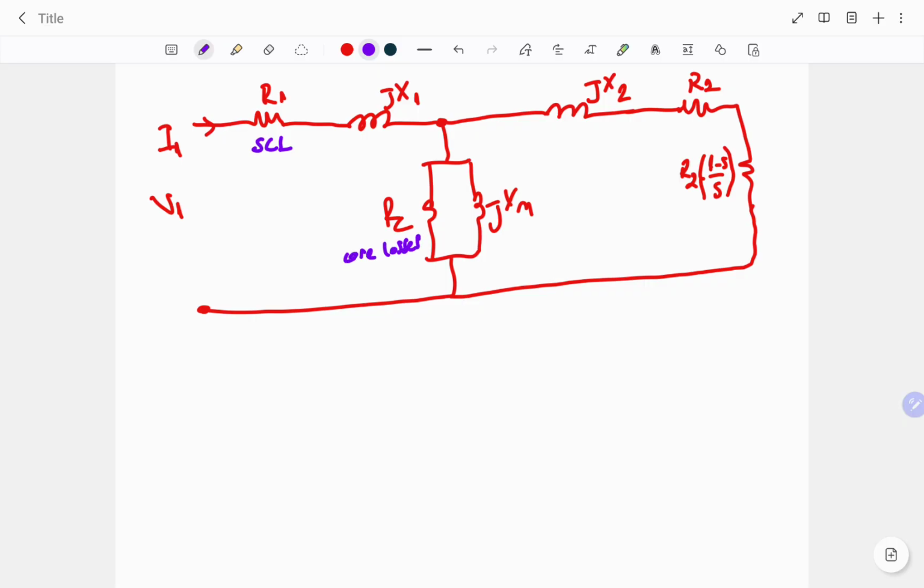So, according to RC, if we can calculate the power absorbed by the RC, we can determine the value of core losses. The next resistance, R2, which is similar with R1, it represents the rotor conductor winding resistance. So because of this, rotor copper losses can be calculated through the R2.